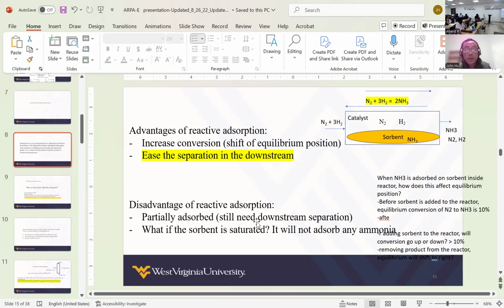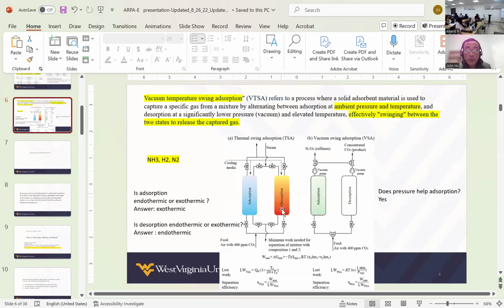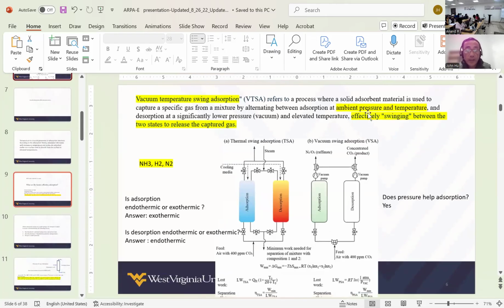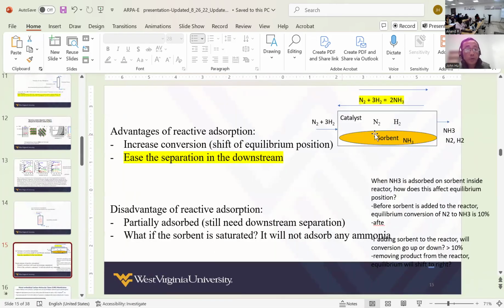So which means you have to put one on standby. You can afford to have 2, maybe 3 or 4 solvent beds, but having solvent and the catalyst in there, the catalyst is very expensive. Building 2 reactors to accommodate solvent regeneration is very expensive. So that's a disadvantage.